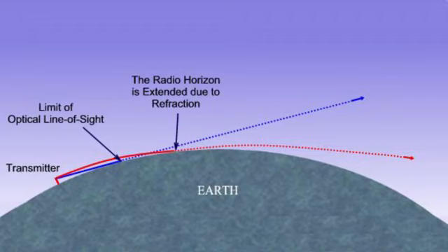However, the higher the frequency, the less they bend. You can extend the range of your communications on VHF and higher frequencies by increasing the antenna height. 10 feet of antenna height is like doubling your power output. This is why a repeater on a high point is so effective in extending range on VHF and higher frequencies. Another thing to do is pay attention to your antenna and feed line losses. Losses are much higher at higher frequencies for the same given length of antenna feed line.